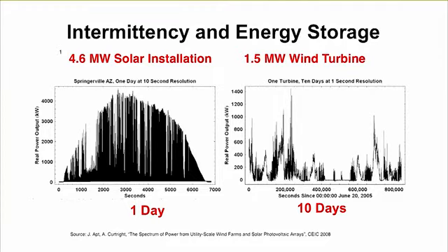Then move over to the right-hand side of my graph, and now it's the wind output for just a single turbine. What one sees over multiple days is that the turbine output, we all know, is weather-driven with respect to fronts and so on, and many ramping events. And these are forecast, of course, but there's uncertainty in forecast. And again, having some backup to make up for forecasting errors is important.